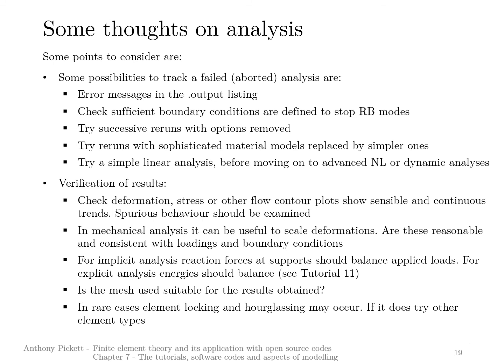Have a look at some of the contours. Make sure that things like heat flow or stress are continuous and make some sense. You don't want locally some kind of spurious behavior due to some local effect that shouldn't take place.